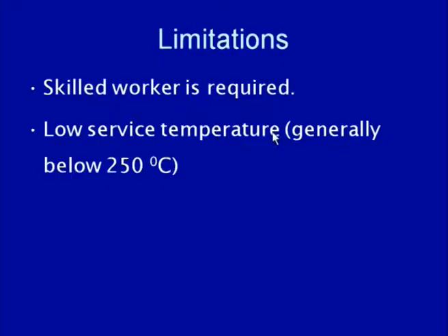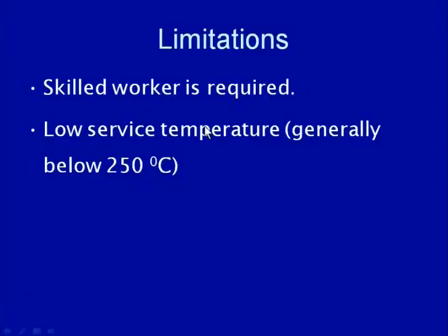The service conditions in which braze welds can be used are generally limited below 250 degree centigrade, because if you go higher in temperature, then the softening of the braze material will start, the joint will deteriorate, and the joint will fail in a very premature manner.